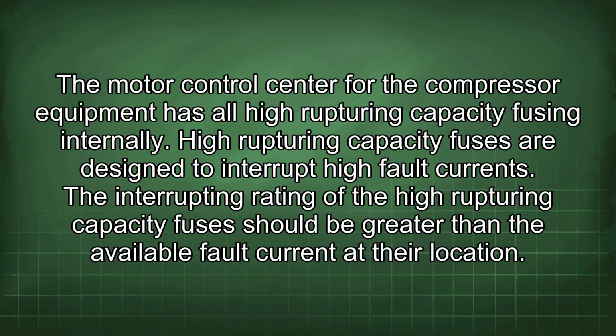The motor control center for the compressor equipment has all high rupturing capacity fusing internally. High rupturing capacity fuses are designed to interrupt high fault currents. The interrupting rating of the high rupturing capacity fuses should be greater than the available fault current at their location.